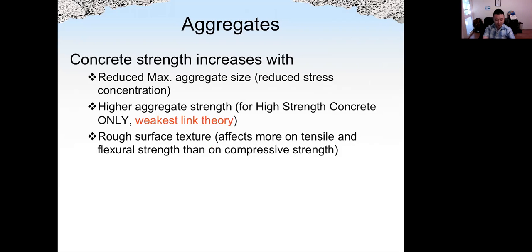Then let's look at aggregate. Again, it's old information. Concrete strength will increase with reduced maximum aggregate size, because of reduced stress concentration. The stress concentration is caused by different E value of aggregate and cement paste.